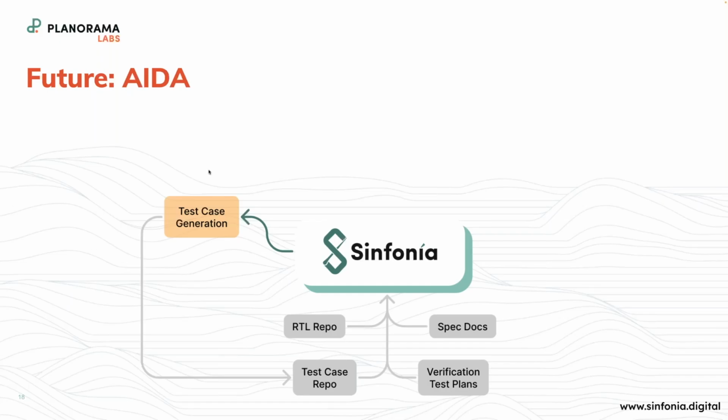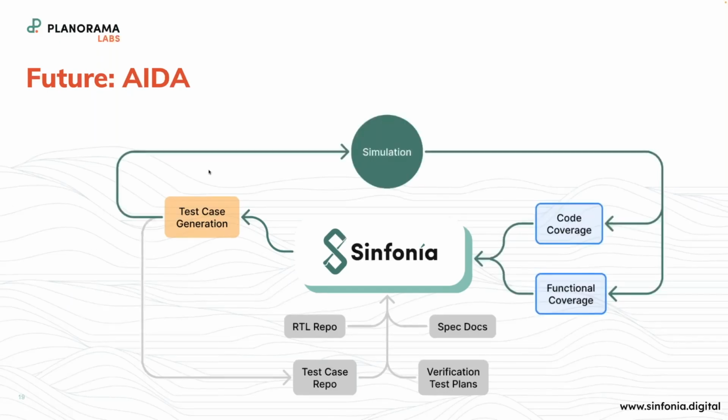And then when you start using stats generated from functional coverage, from code coverage tools, they can see the generation of additional test cases, and this could become a feedback loop. And so now your specifications and all those documents become your golden model in which your implementation is perhaps created and then checked, verified.